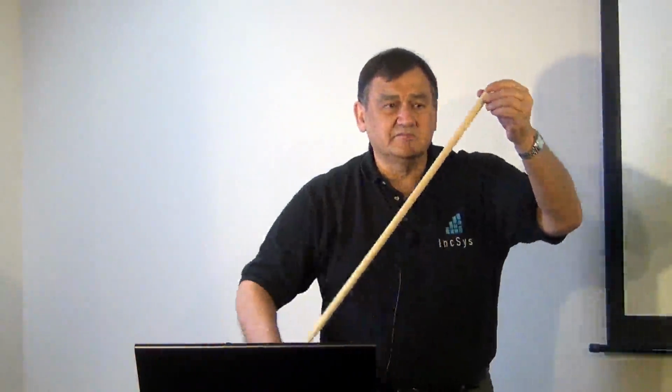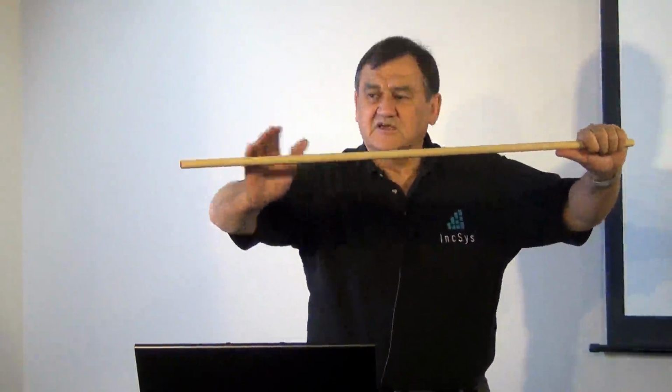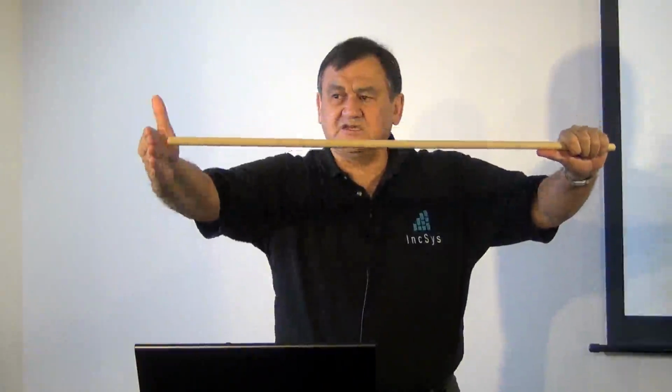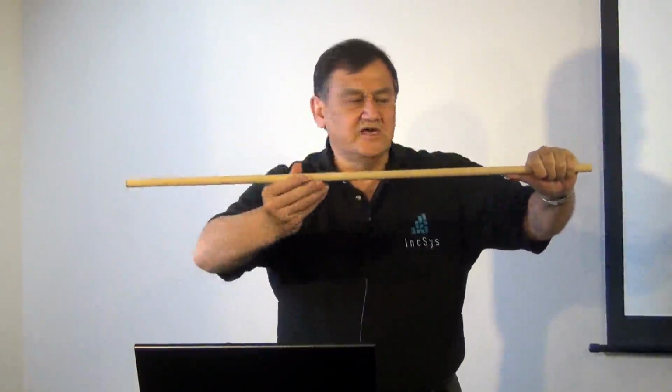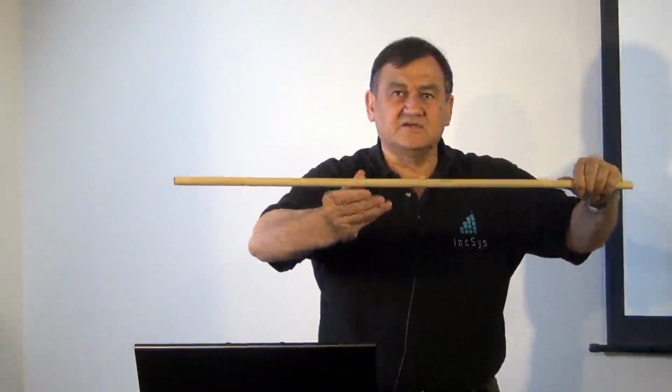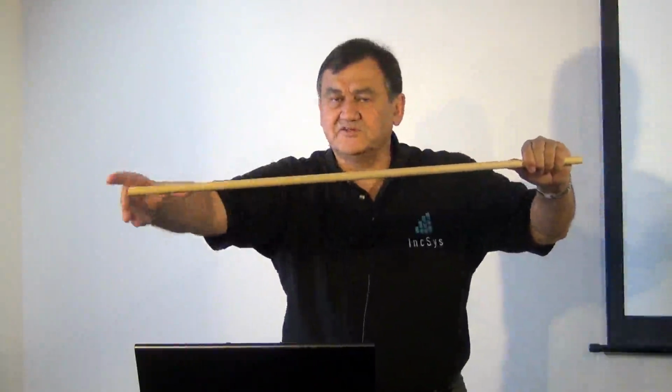So we talked about the analogy with the pendulum. Basically, reactive power flows back and forth. For the reactive power in a generator, we need a convention, and our convention is this: if we have an inductive load at this end that's absorbing megavars, and a generator producing at the other end, the direction of positive flow is from that generator to that inductive load.